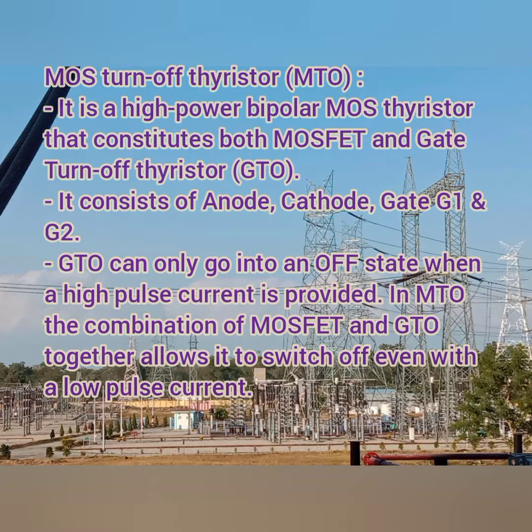So the GTO can only go into an off state when a high pulse of current is provided, but in case of MTO, the combination of MOSFET and GTO together allows it with even a very low pulse of current. So it is very compact and also much easier for handling, because the switching off and switching on characteristics, if you compare with the GTO, are very much upgraded.